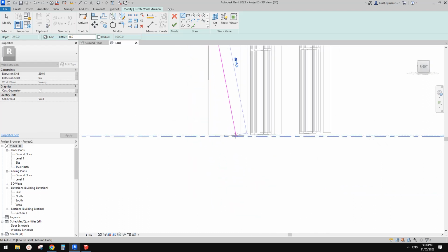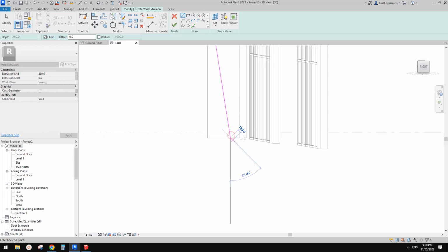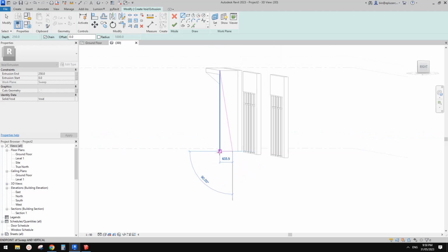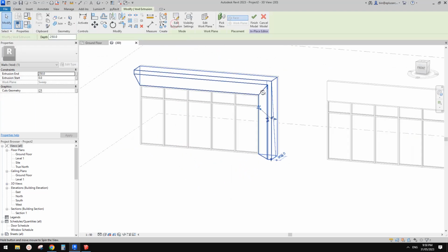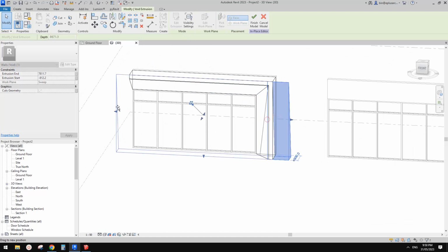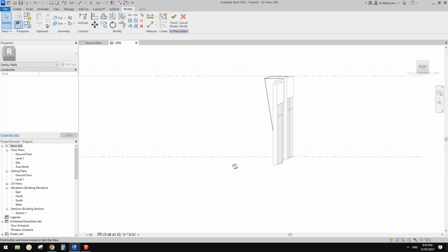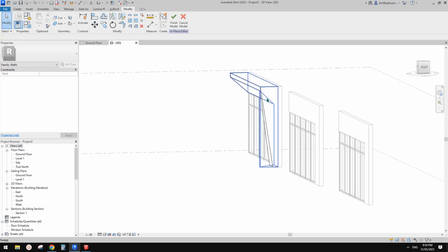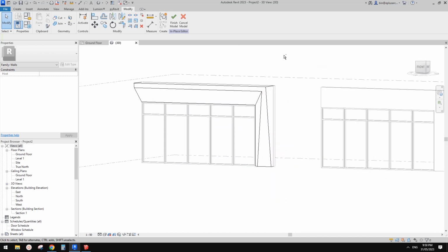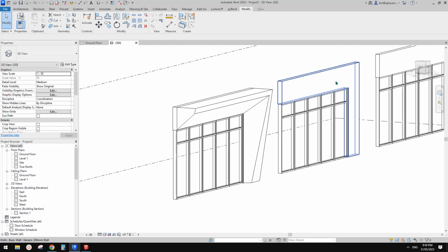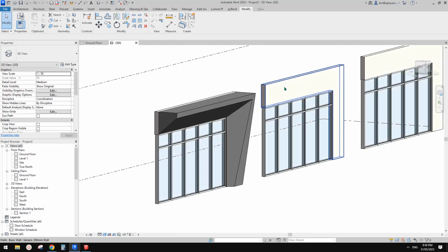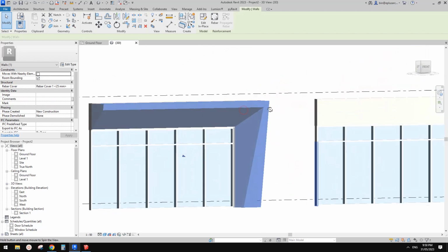Make sure you at least touch the ground floor level, and then you can just go up, and that's it. So finish this, and then we just need to drag this to the other end, click anywhere, and that's it. It will automatically cut the solid. Okay, so this is it, and then finish. Let me change it to shade so you can see that's it.